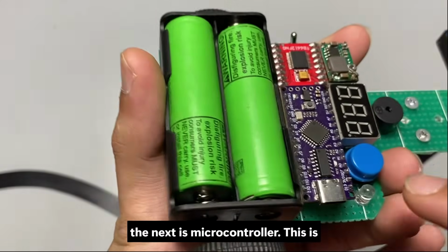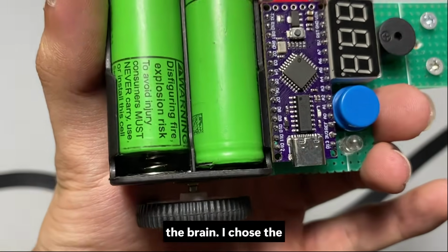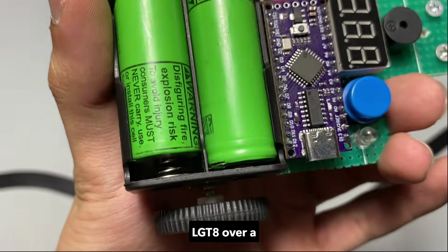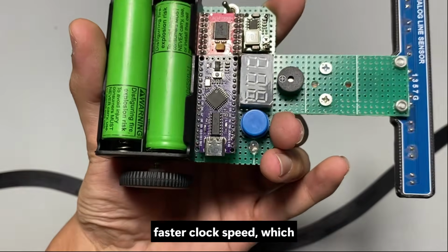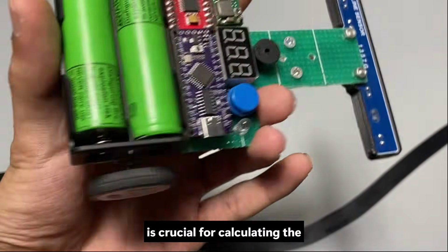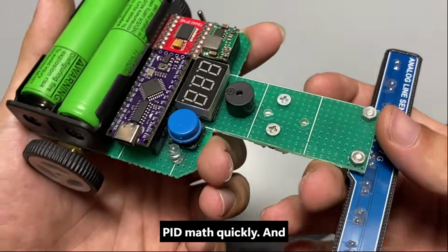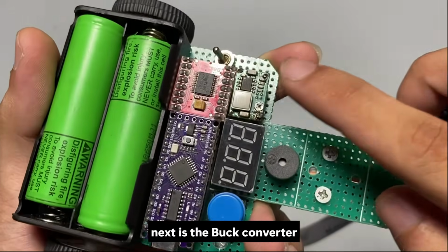And the next is the microcontroller. This is the brain. I chose the LGT8 over a standard Arduino because it has a faster clock speed, which is crucial for calculating the PID math quickly. And next is the converter here.